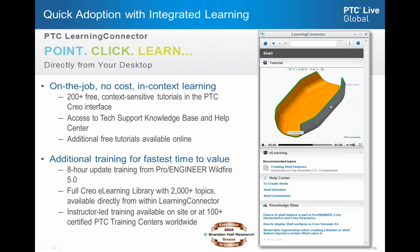Learning Connector is a separate window that will come up next to your Creo screen, but it's linked to your Creo session. So for example, as I'm working, if I decide I want to create a shell, inside Learning Connector it will give you all the information about the shell command. It will give you a little video that shows you how to perform a shell. It will give you links to the help documentation for shell, as well as information from the knowledge base around questions that customers have asked, or certain workarounds that there might be for certain geometry situations.